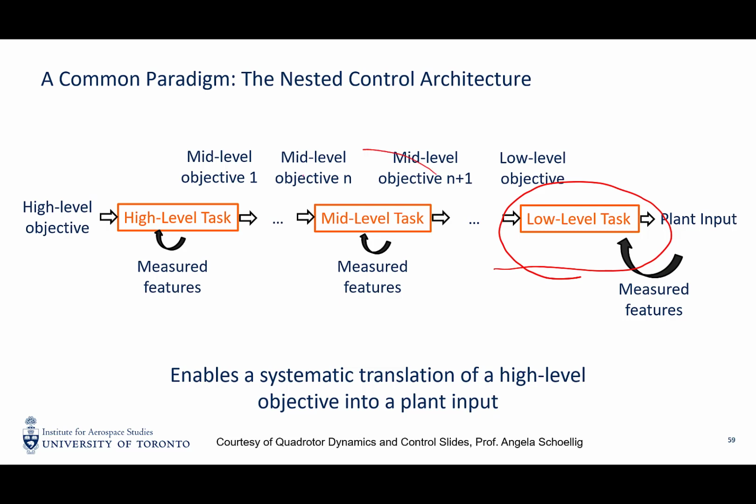On top of that, we build the trajectory tracking controller to generate a desired lift for the attitude controller. And on top of this, there may be some other higher-level missions such as manipulation, swarming, or coordinated flight. All the controllers in this lecture are built upon this nested structure of the trajectory-attitude paradigm.